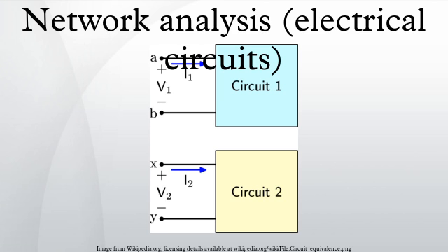Transfer function. A transfer function expresses the relationship between an input and an output of a network. For resistive networks, this will always be a simple real number or an expression which boils down to a real number. Resistive networks are represented by a system of simultaneous algebraic equations. However, in the general case of linear networks, the network is represented by a system of simultaneous linear differential equations.